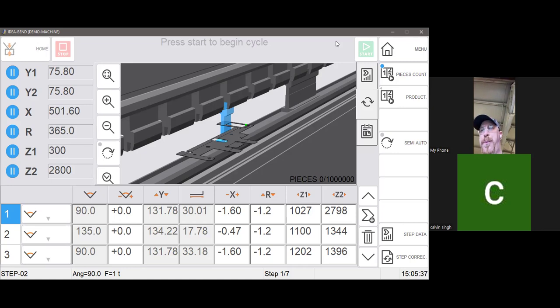Let's say if you're using SolidWorks or Solid Edge, that I think are the most common, you have a special option to include inside the DXF the angle, the allowance, and so on. And in that case, our software will automatically go and look for those data.